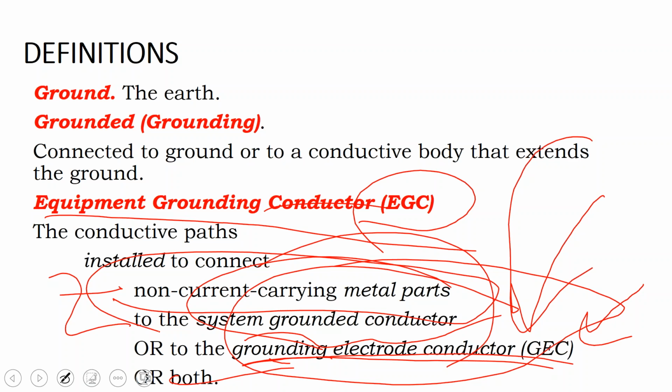of your solar modules. They're not intended to be energized, but they're around all this electricity. And so how do we prevent ourselves from touching a metal box or a metal module frame and electrocuting ourselves? Well, that shouldn't happen if there's nothing going wrong with the system. But what if something goes wrong with the system? That's when we have to be concerned, and we don't want to kill ourselves trying to figure out that there's a problem. We have to connect all the non-current carrying metal parts to ground.